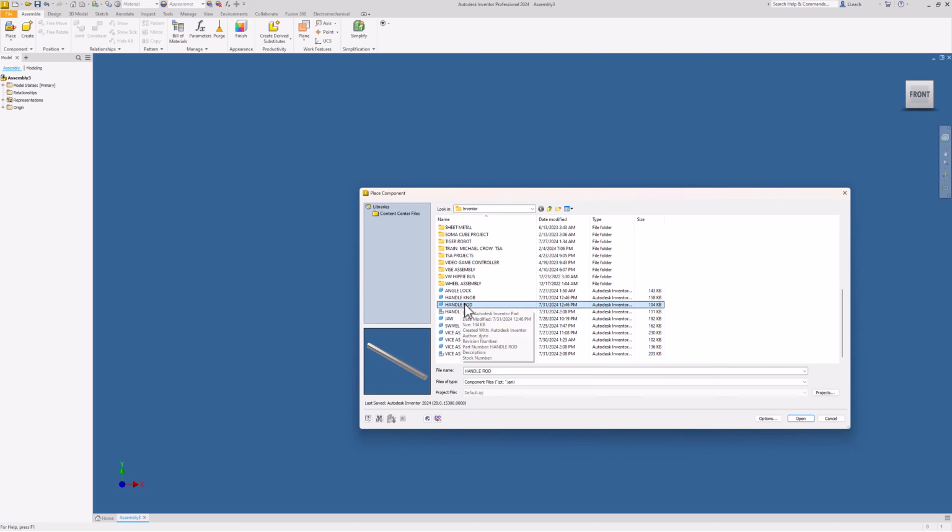So this end is inserted into this hole right here, and then this circular piece sticks out over there. So I'm going to constrain this with the insert constraint. I'm going to select the outside circle of that back face, and then I want to select the inside circle of this kind of hole here. And there we go. Hit apply. Hit the X. So now if you notice that this can move front and back.